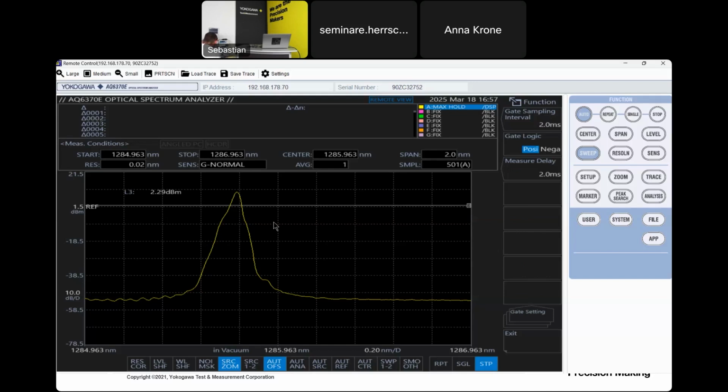If we now do this measurement in the normal external trigger mode, we will see that it would take quite some time to measure the signal, as the trigger signal for the gate mode is much slower than the signal of the pulse source.